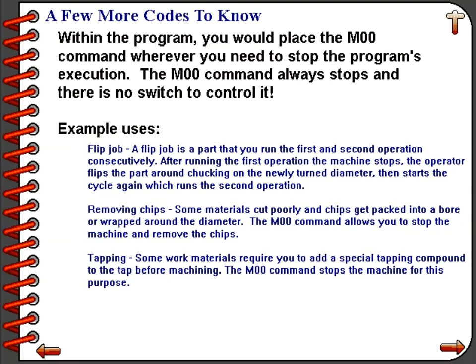So when the M00 command is encountered by the program, the machine will just simply stop. After the M00 command, it is important that you add in all the commands necessary to get the spindle back running again and to continue on with your cutting operations.